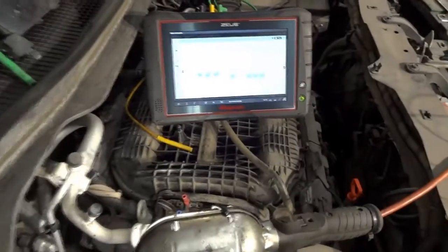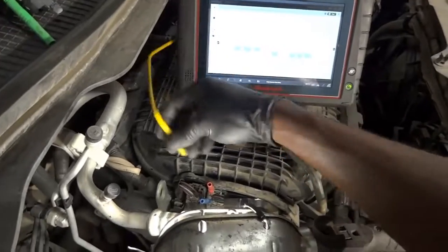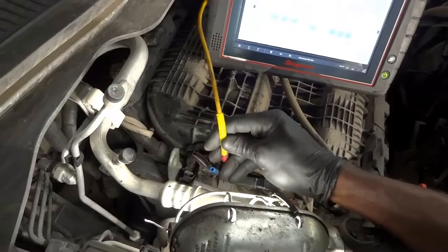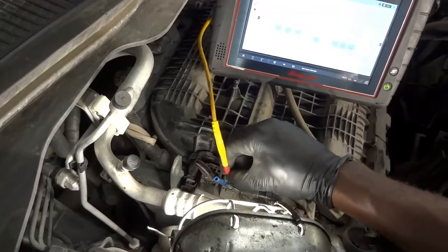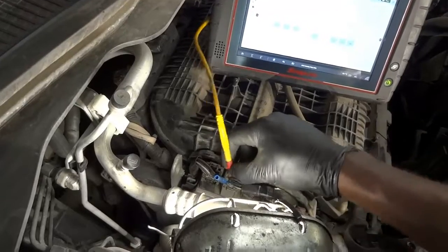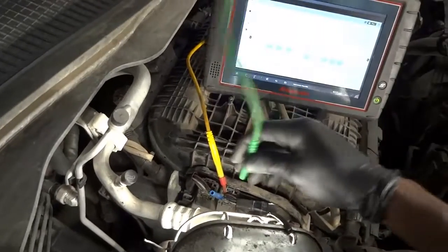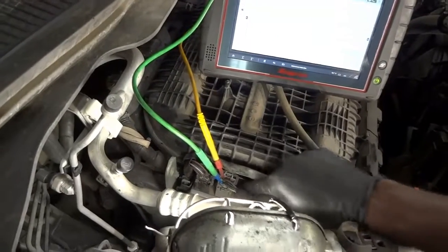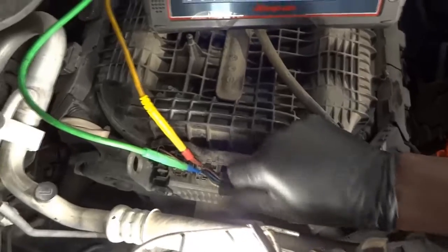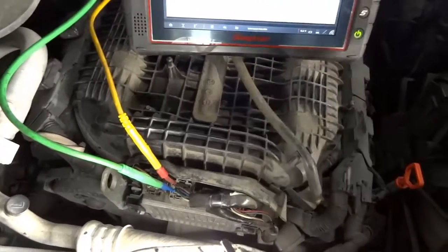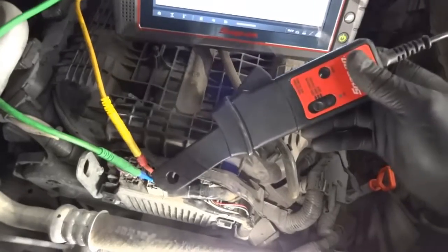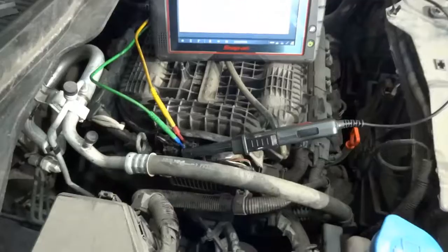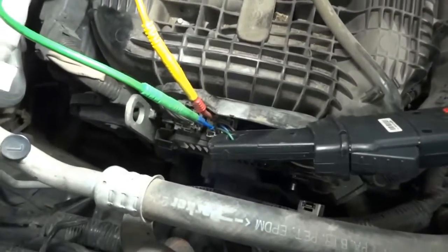So now I'm gonna connect my test leads first. It doesn't really matter which one goes where at this point. Okay, so my yellow lead is going to the brown wire, and then my green lead is gonna go to the green wire. And the other thing I'm gonna do is, let me see if I have enough room here. I'm gonna clamp my amp clamp around one of these wires. So I'll get the amp clamp clamped, and then I'll bring you guys back up. Alright, so I got my amp clamp clamped around the green wire.